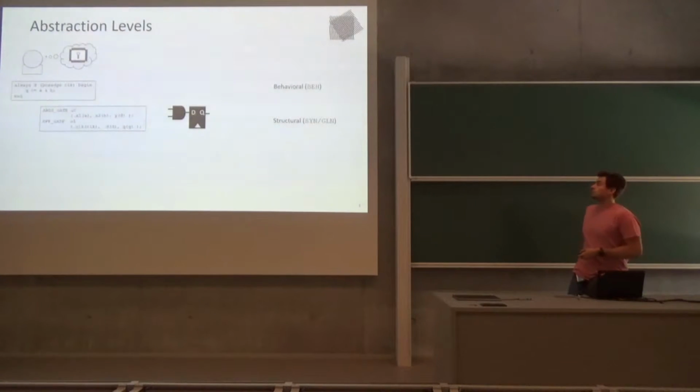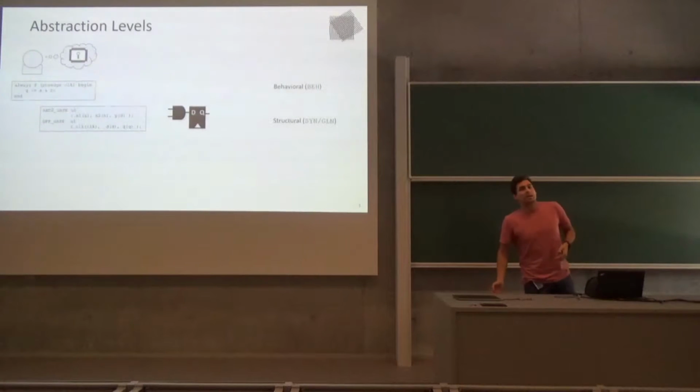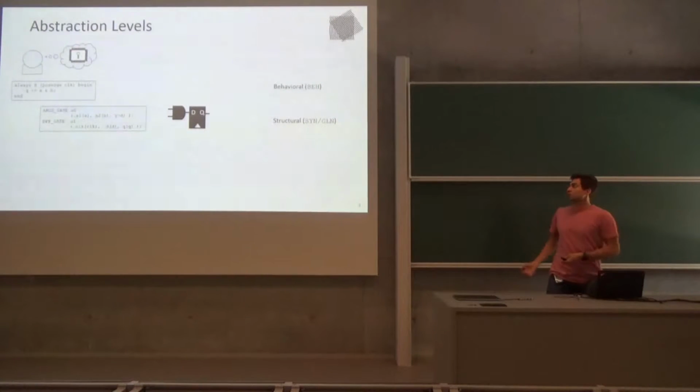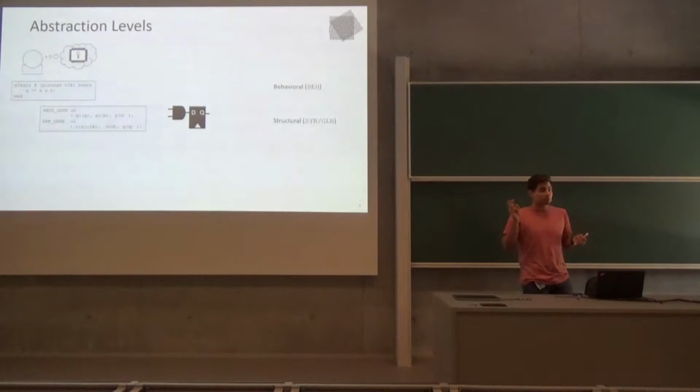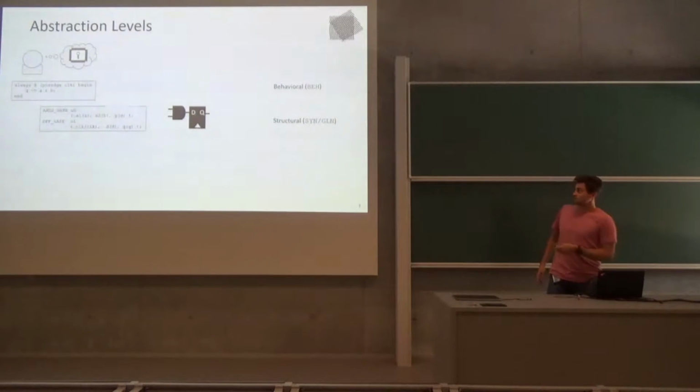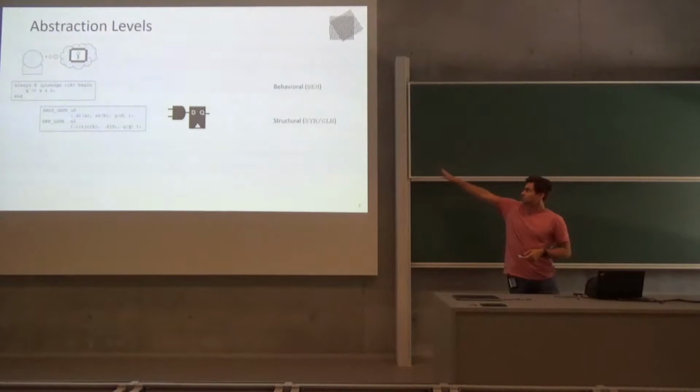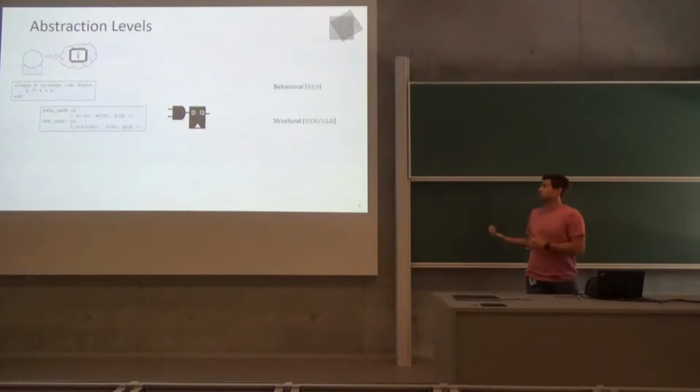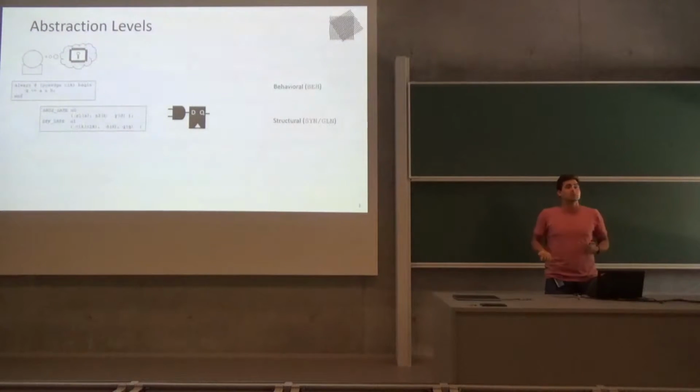Then you use these magical tools to synthesize this code and translate it into things called logic cells or standard cells. In this case we have two: one AND gate and one D flip-flop. This is usually called the structural level. In this talk we will differentiate between a SYN, which is synthesized, and GLN, which is gate level netlist. The only difference is whether you synthesize your design to just a generic AND and D flip-flop, or you're targeting a particular one with a particular drive, etc.